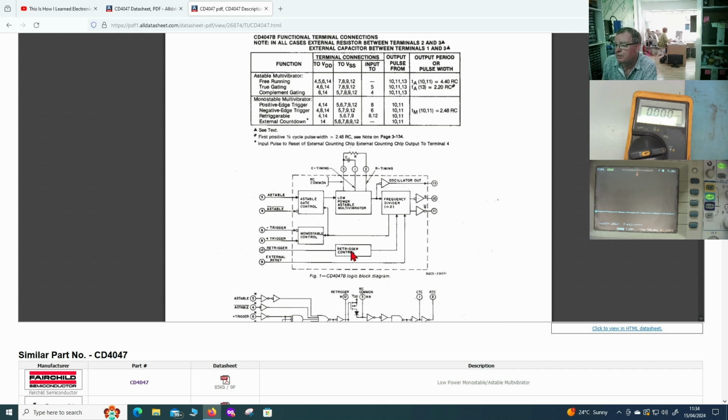It's more possible that there's a problem with this trigger thing, because these effectively are inputs to this frequency divider, which is pins 9, 12, 8, 6. But again, it tells us here 9, 12, 8, 6. It tells us what should be on those pins. So let's just check them all to make sure we're happy.